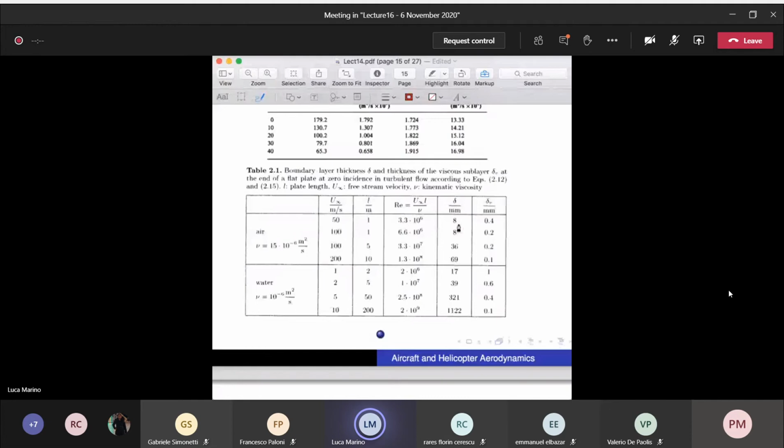So in 10 millimeters, all the important things concerning the viscosity will happen. Instead, if you want to see some changes along the X direction, we have to wait for 1 meter. So the changes of all the physical quantities, the U, the pressure, in the X direction will be over a scale of 1 meter.